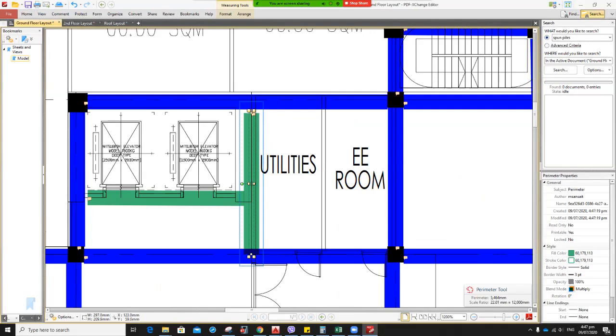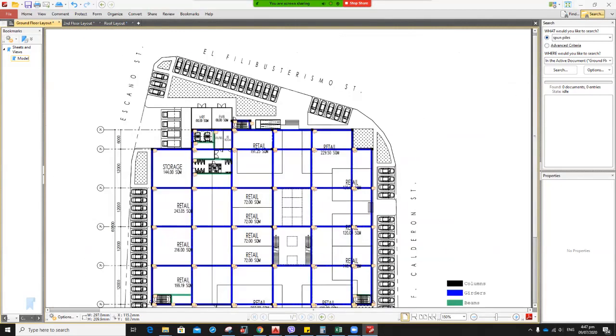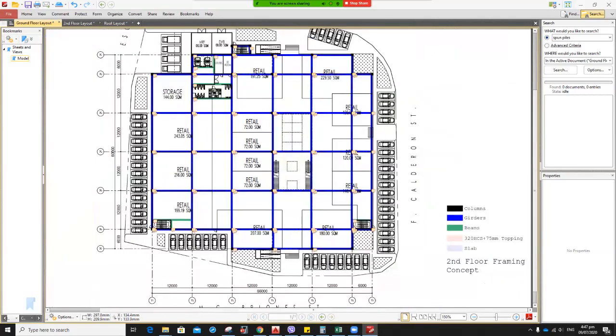We made the slab suspended since we were elevated by 1 meter. So we don't need to do a lot of excavation and backfilling at the bottom of this slab. So we can use again the hollow core slab and then the regular slab.